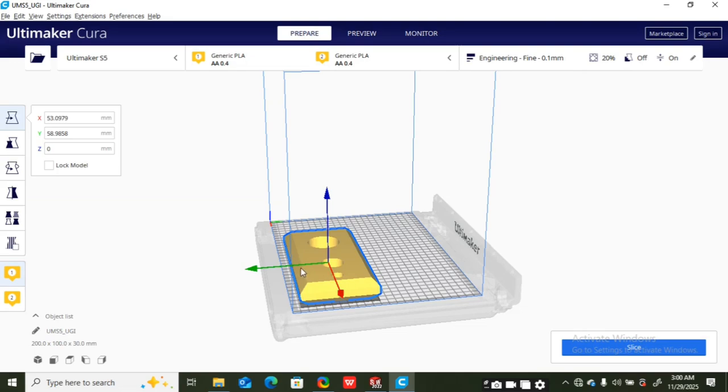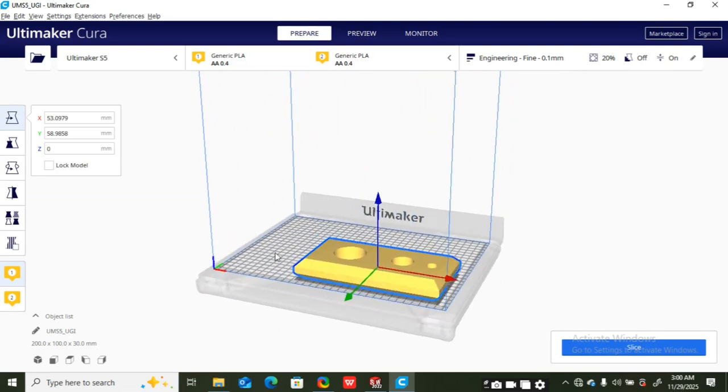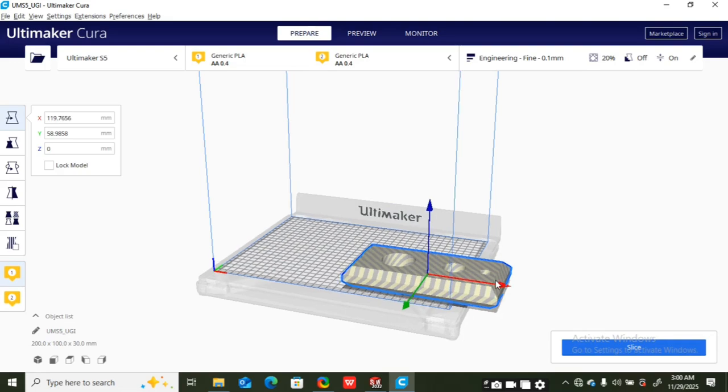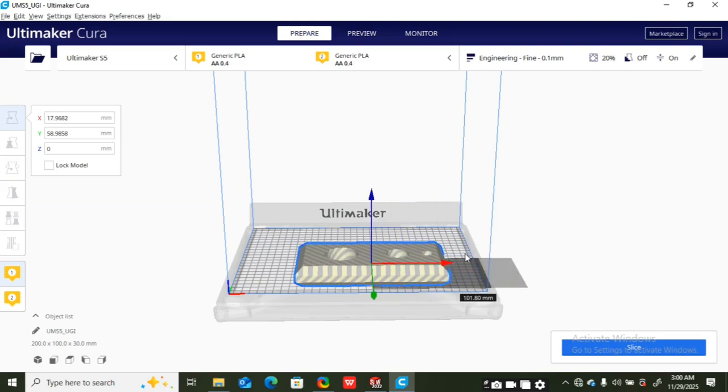And there's another thing that you need to observe. Now you can see that this box has some perspective lines, right? This is actually the boundary of the whole workspace for the 3D printing. So if my model extends far beyond the perspective line, you will see that the model has turned to something different. That is, the model cannot be 3D printed. The only area that the 3D printer recognizes is the work area in between this particular box and the height of this perspective line. Anything above it won't work, so you are left with the option to correct it back.